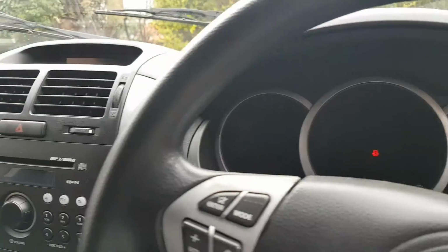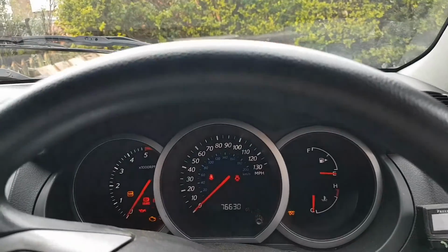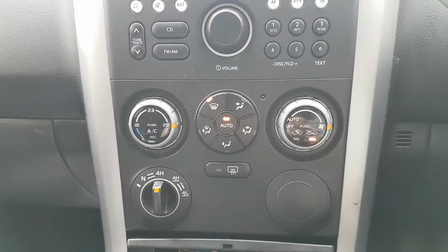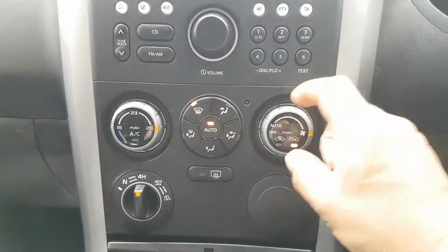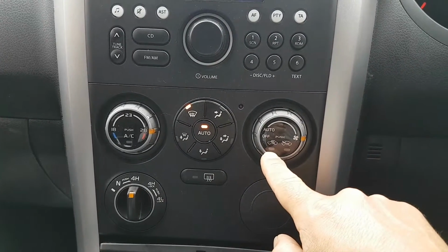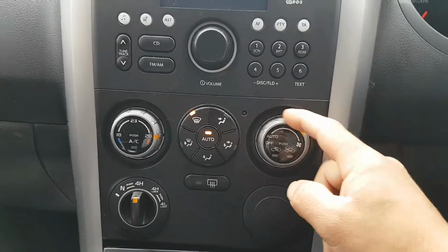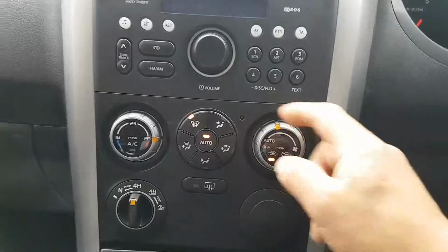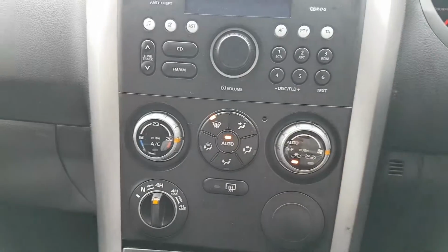And the problem is, I'm going to show you. When I turn my ignition on, so my ignition is on, I have the following. It's an HVAC problem, and what you're going to see in a minute is the following. This is at full speed, it doesn't work, and look at that, it starts to flash, and my fan just doesn't work. It's that simple. When I try to move this from one to the next, it actually moves, but then it just doesn't run. The fan does not run.